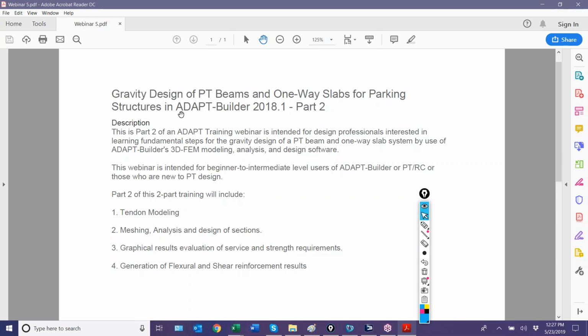So we're really going to focus on first satisfying the PT result, which means we're going to check serviceability level conditions for the slab and the beams. We might check just some initial deflection, not initial as in the initial stress condition when we transfer the force, but just what is our deflection under linear elastic conditions for total service. And we might make a prediction of long-term deflection just by applying a multiplier on top of that and see where we're at. So we'll also check precompression, balance loading, allowable stresses, and kind of give you a flavor of what that check is like.